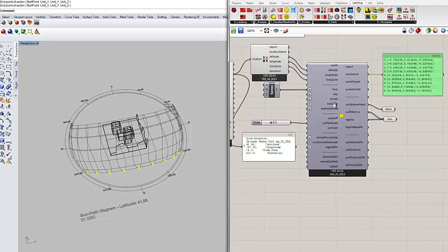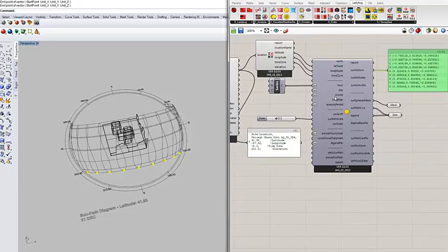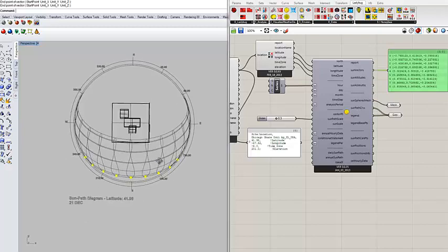I think this is something interesting about having a sunpath in Grasshopper, because as soon as you get the sun positions, you get the vector for that. But in a normal way, you have to read the sunpath, find the degrees, and then you usually don't get the vector, but you calculate the HSA, horizontal solar angle, and VSA, which is vertical solar angle.